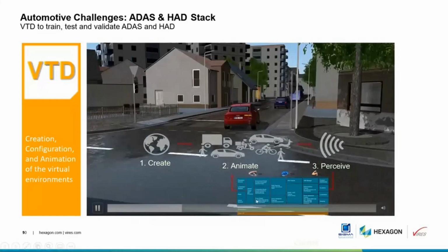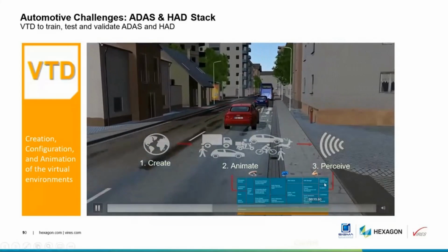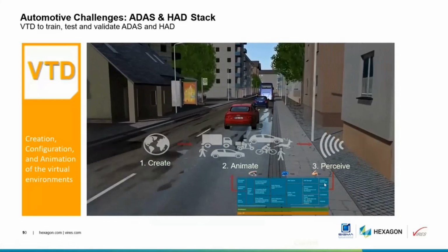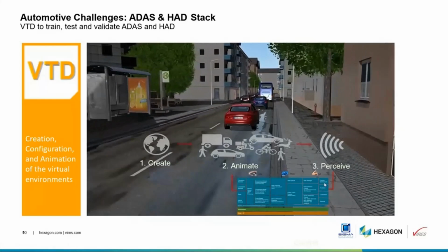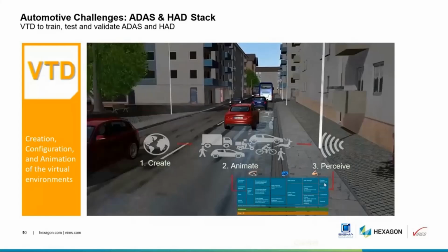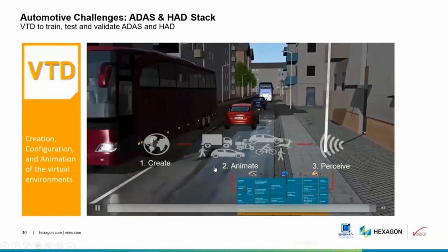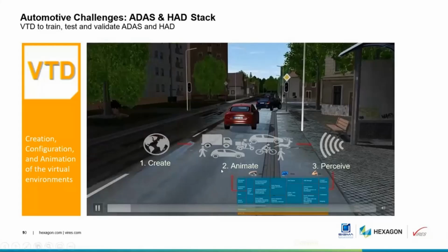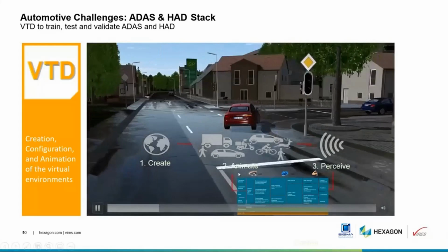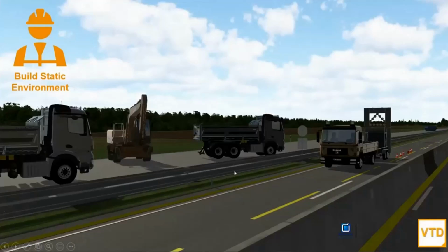The data goes to your act control, like driving functions, lane keep assist, AEB, ACC. Then you can give those commands back to your ego vehicle or other traffic participants in the traffic scenario editor. So you could create these kinds of static environments with advanced things.